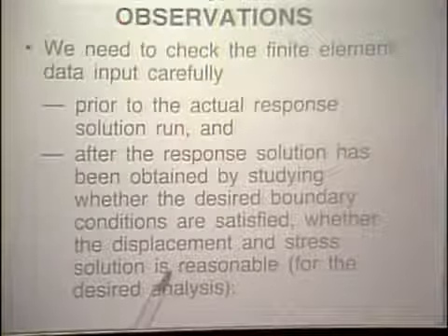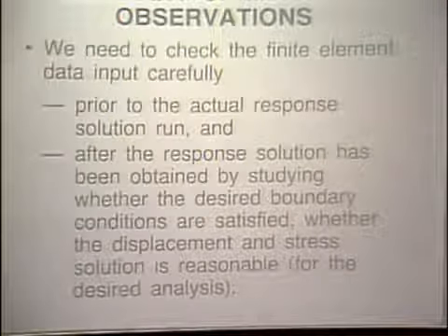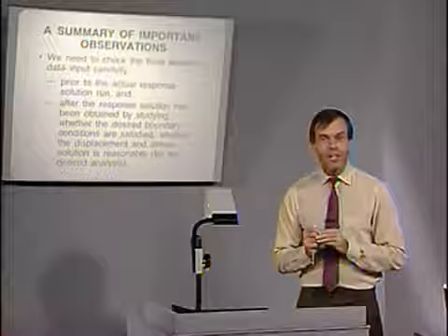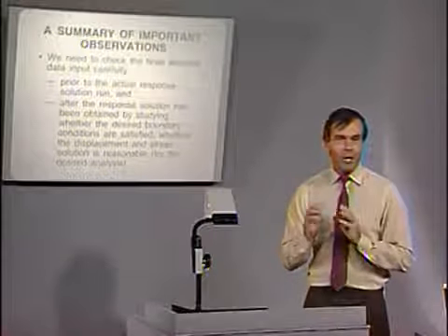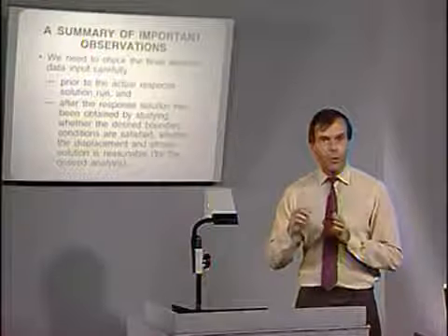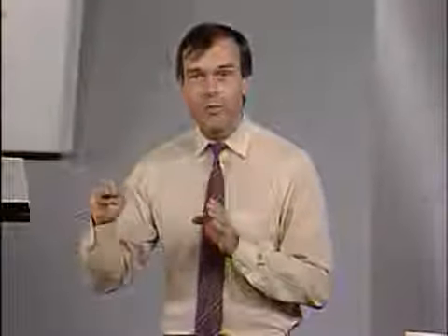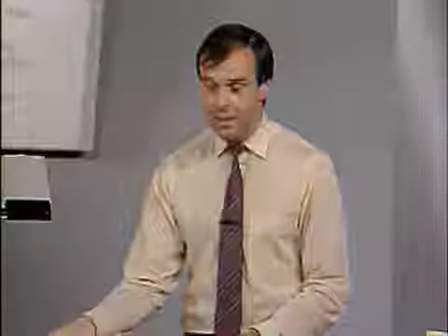Of course, the same holds for the stress solution. You remember that we looked at the stress plots for the mesh that was fixed at the bottom, and we could directly see there were errors there, in other words, the error of having fixed the boundary at the bottom of the plate. So this step is most important, and we have seen an example in the analysis that we just completed.